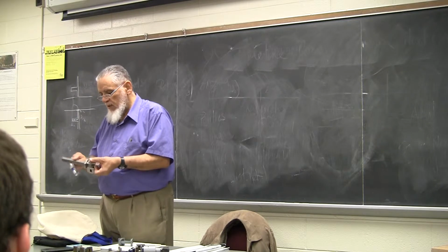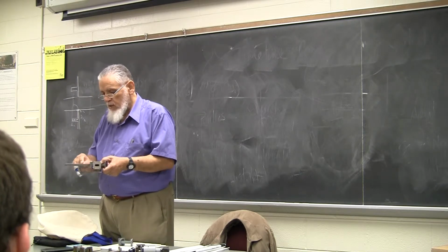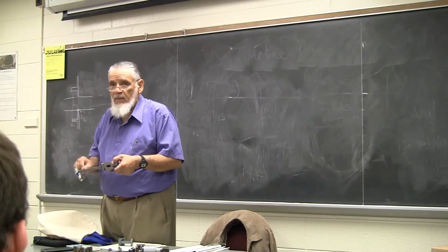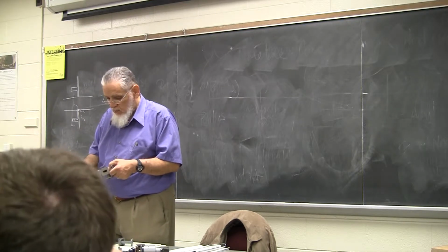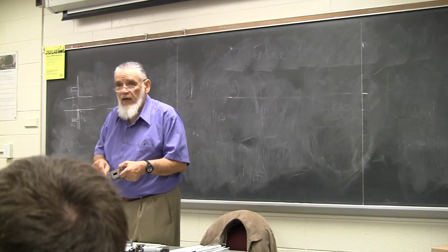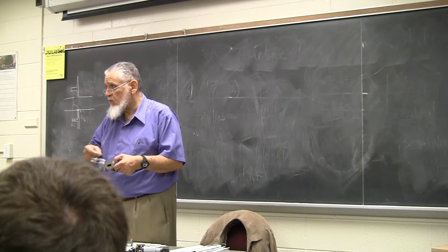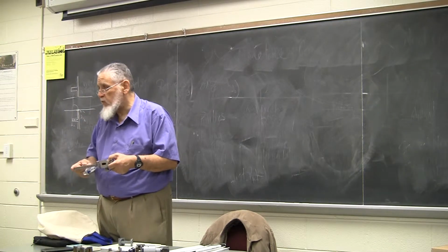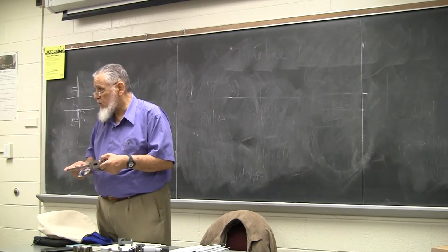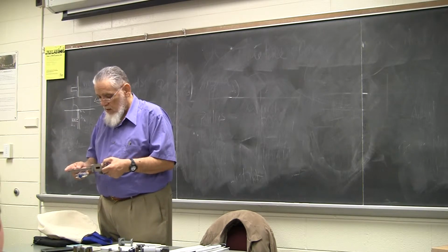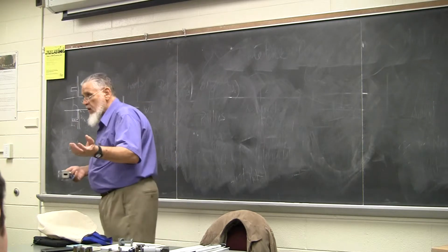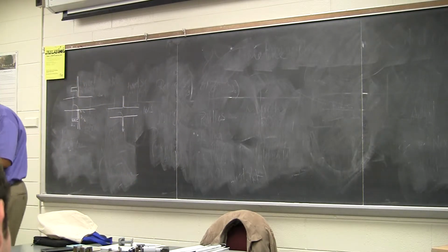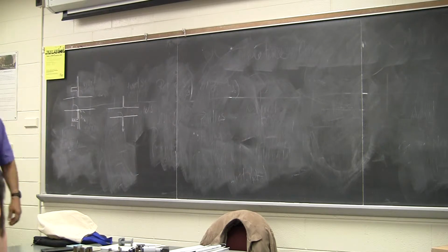Now, this one here is a matched termination actually. This one here has some resistive tapered core inside, all right? So it absorbs the energy over distance and eventually causes a full match to the impedance there. So it absorbs the energy and sends very little current back. They are just connected to each other, so we'll just leave them together here.